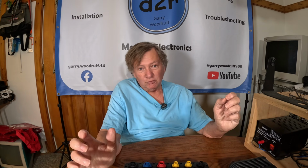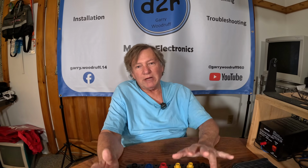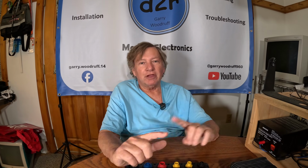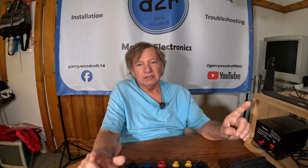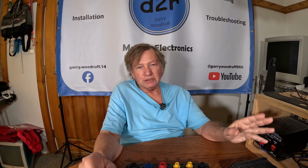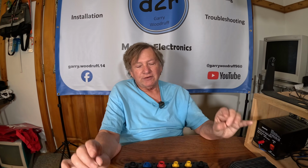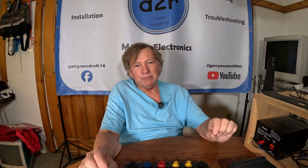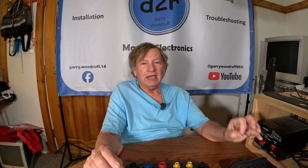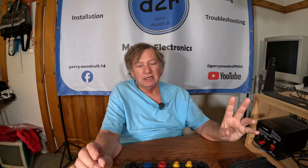And then when I put the new waypoints into that unit, as soon as I have the other ones powered up, they all now have the new data, okay? So basically, you turn everybody on, you delete the old stuff, you load up the new ones, and boom, they're all populated. And that's a very, very handy thing. So that's a major, major difference between waypoint sharing on Ethernet and NMEA 2000. Okay, so just be aware of that difference.